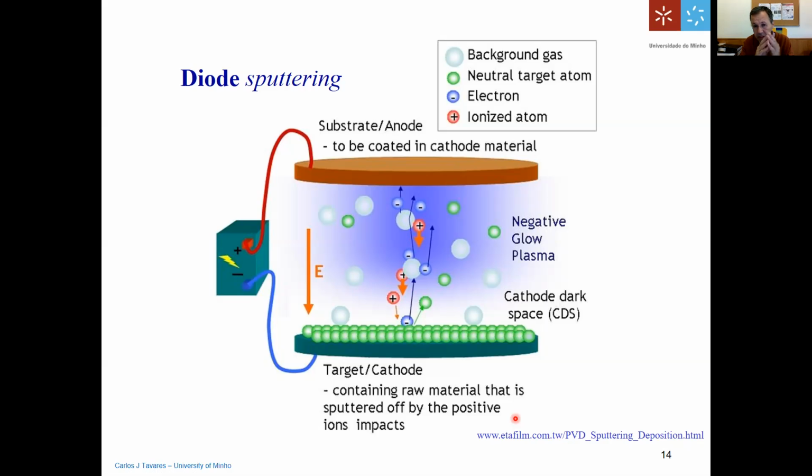So what happens is that when this current is passing through the filament, it can also eject some atoms of tungsten. And so these atoms that are ejected will coat the inner side of the bulb, okay? And in this process, you're actually making a physical vapor deposition. And this is what happens with bulbs when they reach their lifetime, when they cannot emit light anymore.